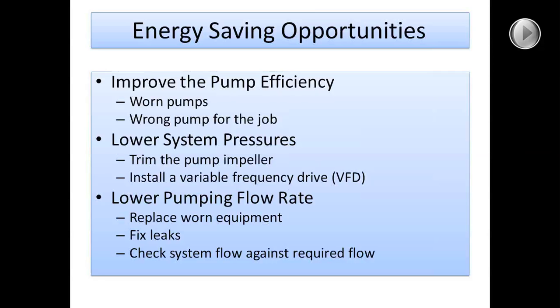But if you start reducing your flow rates, we looked at the pump curves yesterday, usually your pump pressure would increase. And you don't need those higher pressures at lower flow rates, and so a variable frequency drive will maintain a set pressure. That's the most common application. You program that drive to maintain a certain pressure at your pump all the time. It may be 50 psi, and no matter what's happening downstream, that VFD is going to try and control the speed of your pump motor to maintain that pressure.